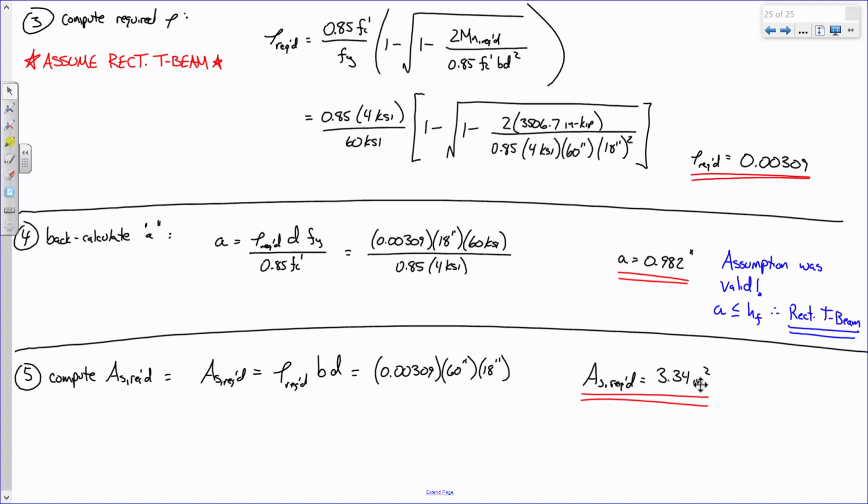I don't remember, what was the pattern we came up with? Does anybody remember that from last time? Was it like 3 number 10s or something like that? So, analyze the T-beam, assuming there are 3 number 10s, compute your efficiency, verify your ACI requirements, and if it works, there's your answer. You use 3 number 10s. It's that simple.